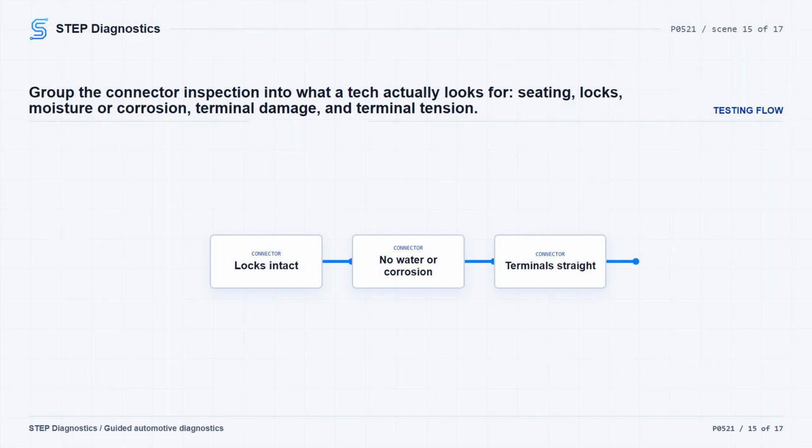If the PCM did not recognize the jumpered low signal, go through the related connections closely. Disconnect the PCM connectors, any related inline connectors, and the related component connectors. Inspect for poor connector installation, damaged locks, corrosion, water intrusion, seal damage, bent terminals, overheated or discolored terminals, terminals pushed back in the cavity, spread terminals, and weak terminal tension.